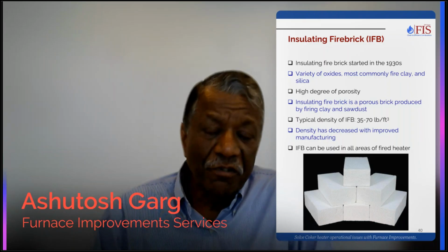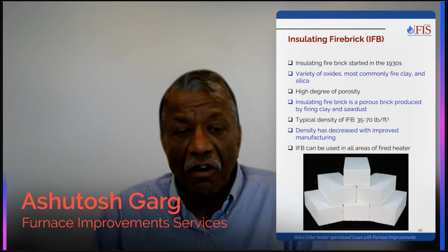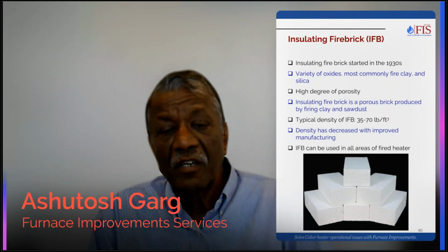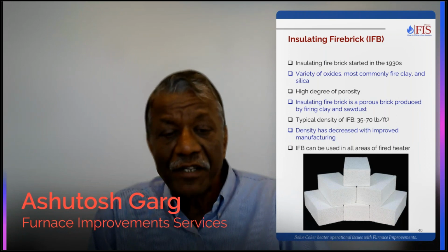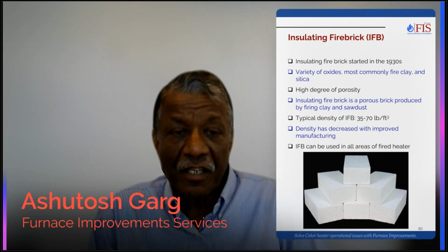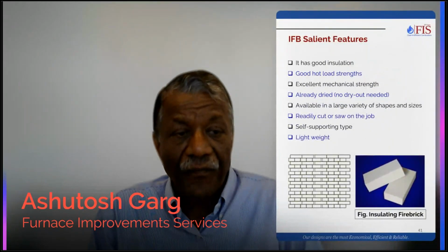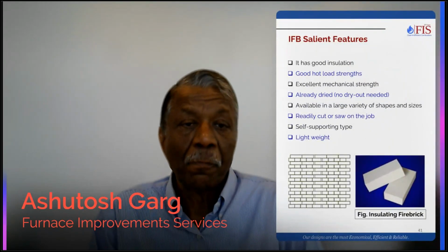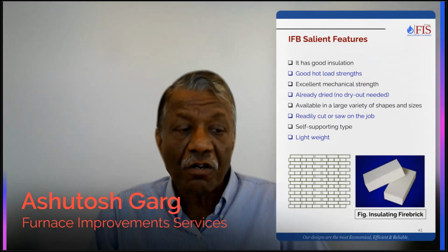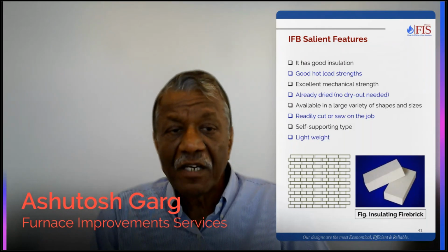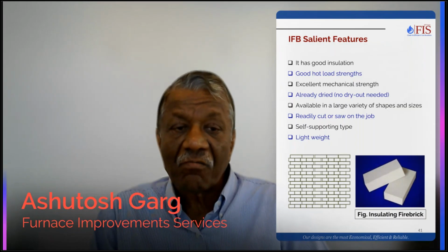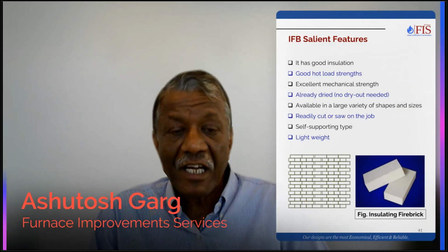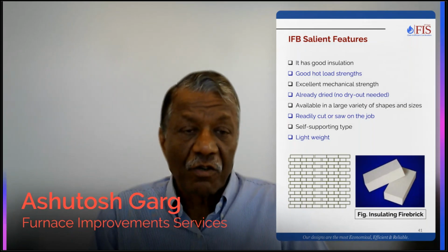In India, we used to see IFB a lot more often in the heaters, but in US, IFB is not used basically because of the high installation cost. Several good things going for it. It has good insulation, good hot load strength, already dried out, available in large variety of shapes and sizes, readily cut, you know, self-supporting type, lightweight. So very, very good material.